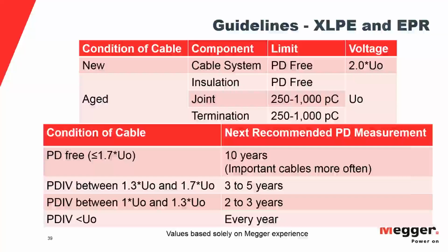Is there any difference in VLF testing using a sine wave? VLF sine is a perfectly acceptable wave to do withstand testing that's recognized by IEEE, as well as cosine rectangular too. So sine wave is a perfectly fine wave to do withstand testing.